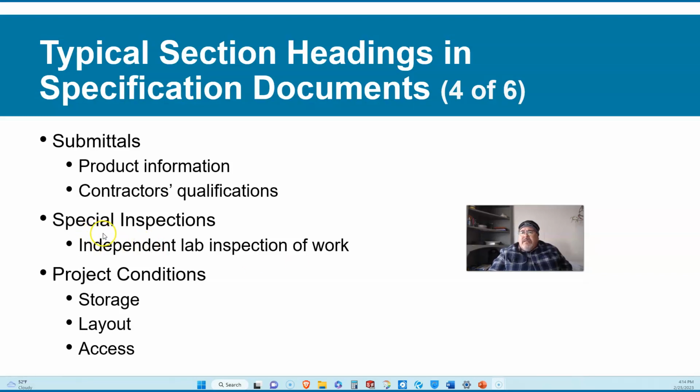Special inspections have to be done on those bleachers because they need to have a certain level of quality, and so they will do inspections not only for the quality, the installation, the material, the workmanship, but they'll also make sure that it has the appropriate type of seating for accessibility, and those other requirements. So special inspections might be a requirement, not only by the state, or it may be something that's required by the owner.